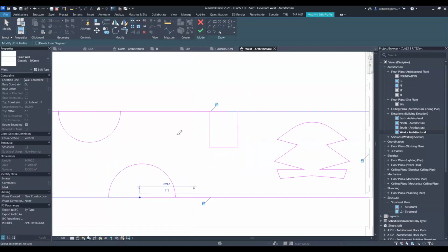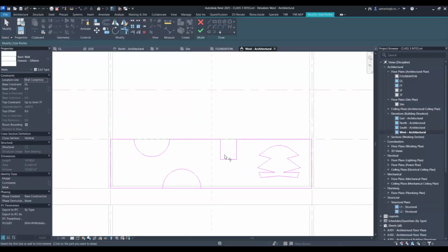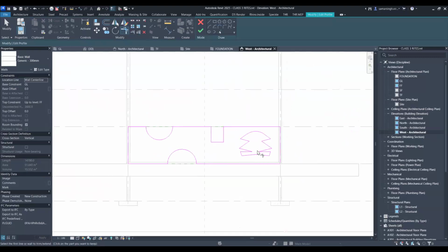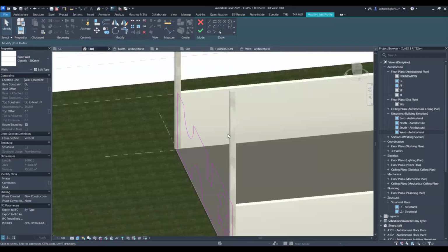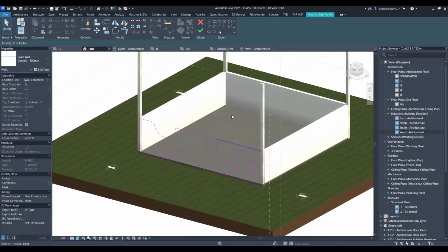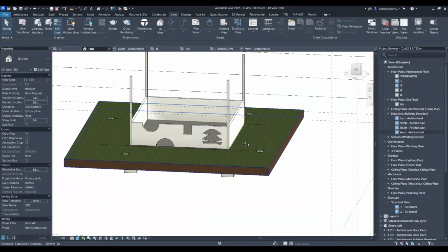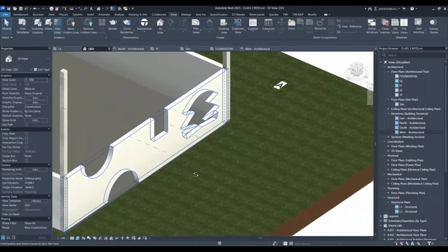You will just see in a minute that after cutting all these lines from here, now when I do TR and just keep the lines that I want by clicking on the lines that I require, I will be able to make a connected loop like this. Now you can see we have made quite different shapes, and let me just go to 3D and press on tick. Here you can see that whatever profile we made has been converted into a wall.